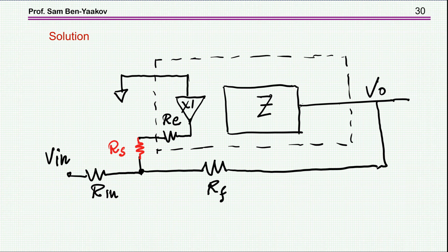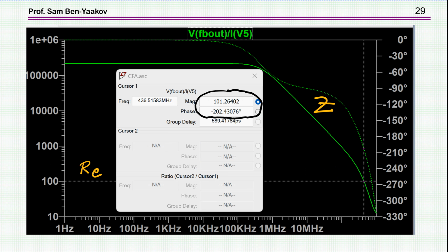Now the remedy for this is actually to add a resistor here. Now, as we have seen before, the value of this resistance does not change actually the transfer function in closed loop, RF over Rin in the case of just an inverter, and the same will happen with an integrator.